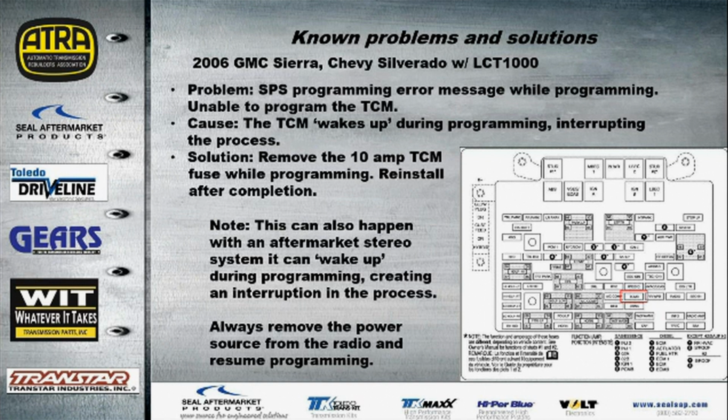We're going to knock them out with a hammer and take out the TCM B fuse. And basically, once programming is completed, we get that message that programming has been completed. Then we can put the fuse back in and allow the computer to wake back up. This is one of those things that just happens with this specific model for some reason. Also keep in mind, if there are aftermarket devices installed, this can create the same symptom. So we might be looking for an aftermarket device causing this.